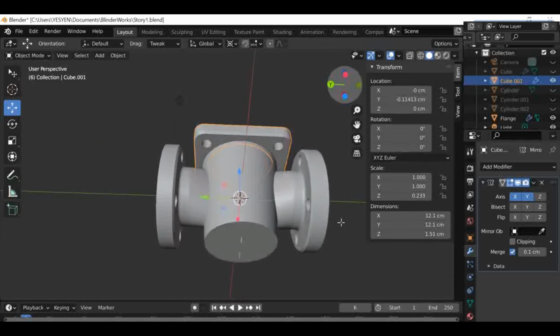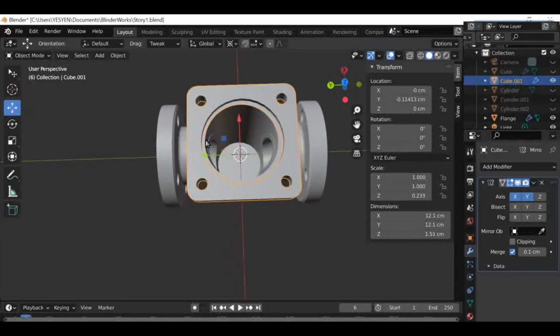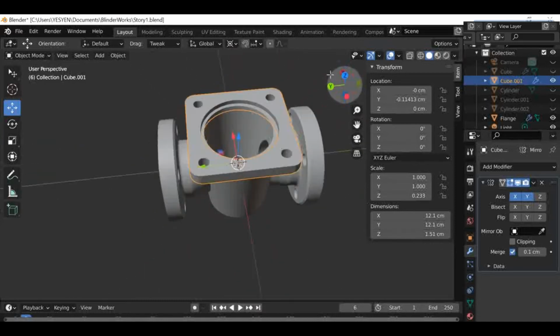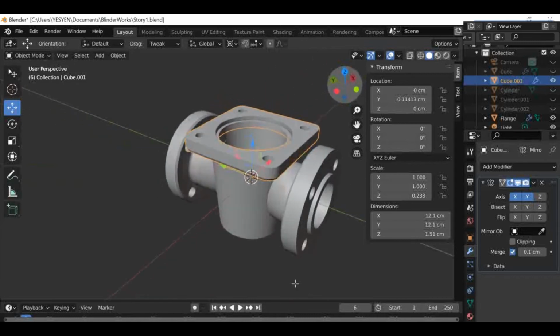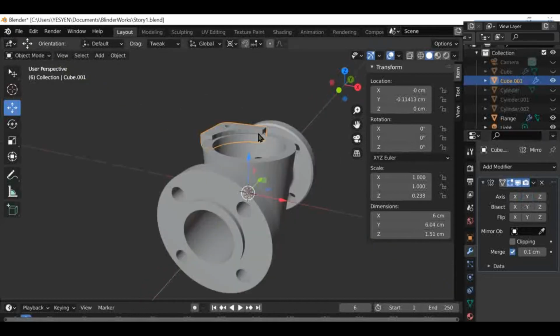Fine. We have added a flange and there are 4 holes equally spaced, and we availed a groove here so that the bonnet flange that's going to sit over here will get centrally located. That's the purpose of this groove. That flange will have a projection. Beautiful. You see that, you carefully see that it has got ridges.